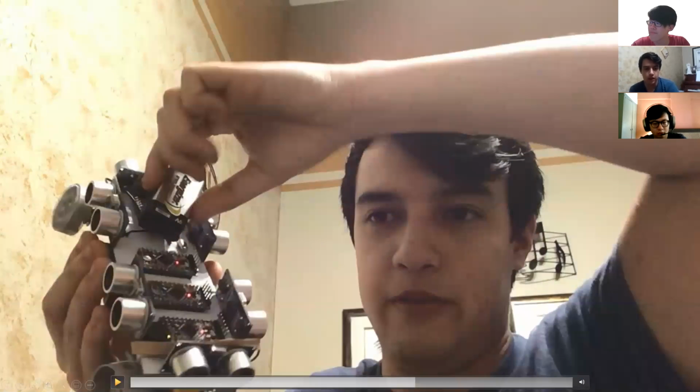It's a 9 volt. I don't know if you saw that battery pack underneath. Basically what happened is with our voltage divider, we had way too much voltage drop over the resistors that we had. So I scrapped the old idea. Instead of having a 9 volt to 5 volt drop, we just had the 9 volt, and then a 4.5 volt with 3 AAs in series, and that was used to power the system. It was interesting because the entire system could run off the 4.5 volt, but the motors were not nearly running at full capacity.